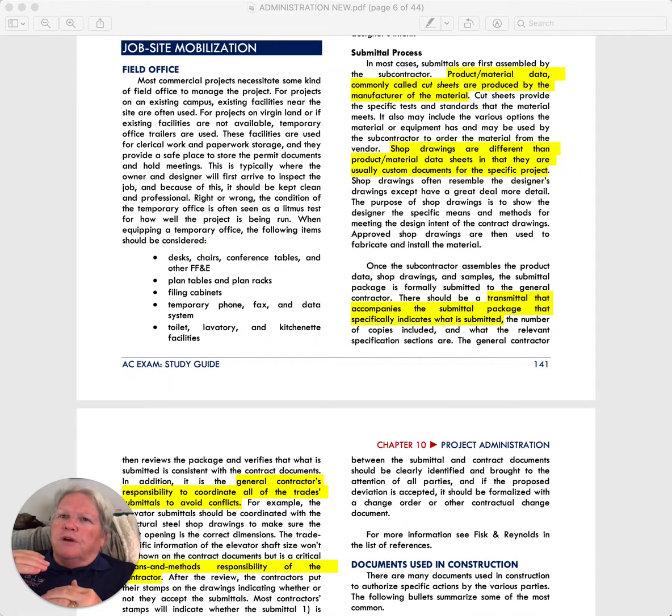But they take it to, I would say, probably a level of completion, architectural design drawings, CDs, construction documents, to about 80% complete at best. Submittals are the product material data and the shop drawings that start looking at 1/4 of an inch to 1/8 of an inch tolerances between materials. And sometimes you have to verify certain dimensions.